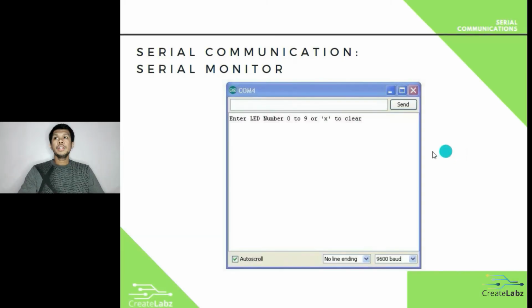Now let's learn about basic tools and functions that we often use in Arduino. Note that I will be discussing only a few, since you will encounter more along the way on the next modules. So first is the serial monitor. This is an important tool that we can use in order to check what's happening in our code. So we can print out messages here such that we know what is the output, for example, of a sensor reading or the input from a specific pin.